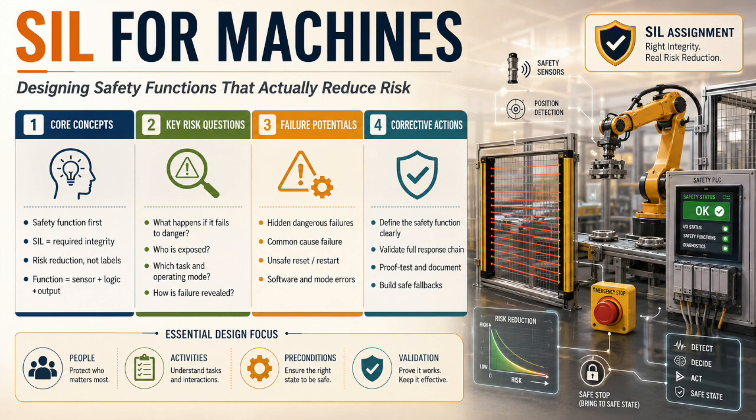That question opens the real safety picture, because the person most at risk is often not the normal operator. It is the person clearing the jam. It is the person reaching into the guarded area during setup. It is the person cleaning around residual motion. It is the person troubleshooting with covers open. It is the person assuming the machine cannot restart. It is the person trusting a safety function that has silently failed.